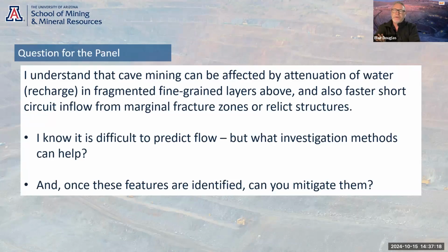But obviously if you start hitting large structures underground and large water flows are in there, you've got to get pumping equipment that's capable of dealing with it. But you also have to recognise that you could have very high pressures. So when you're drilling through this stuff, you've got to be prepared for high pressures and the safety issues that come with that, and making sure you can seal in. If you are using drains, seal them in properly. Make sure that you've got control on them.